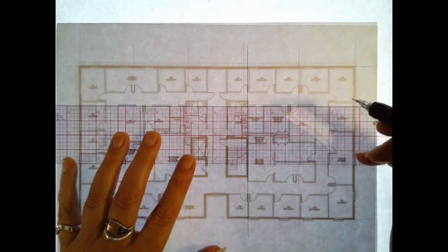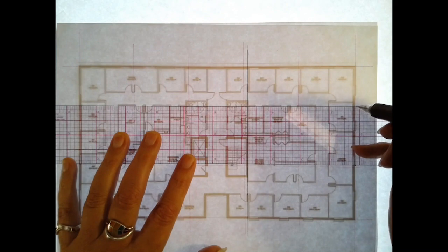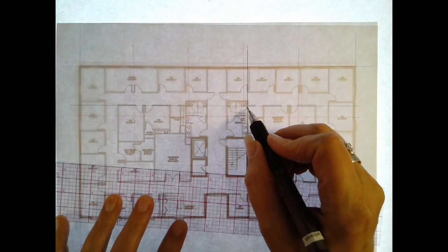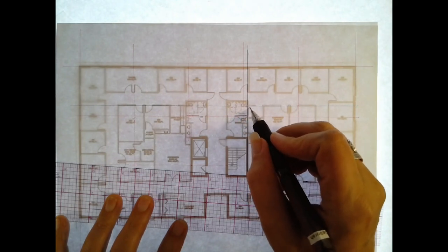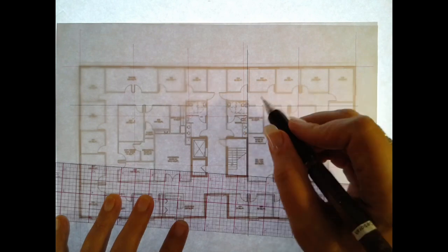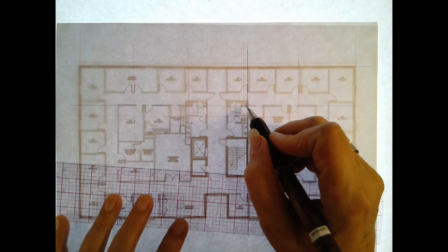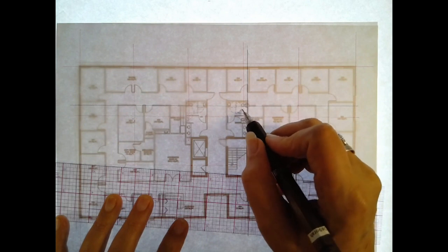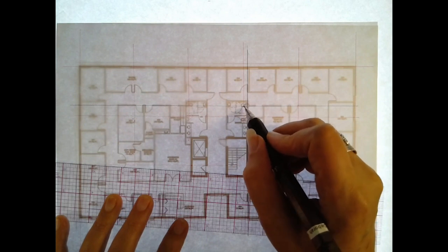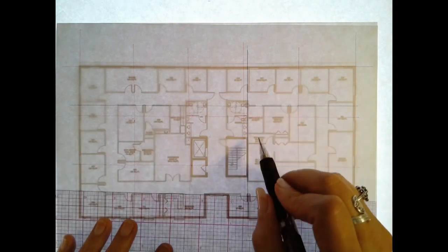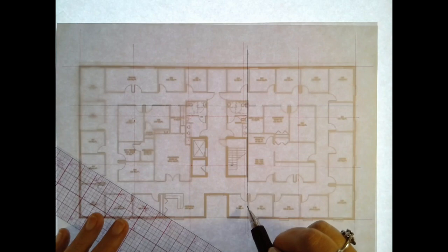We might have to make some changes to the architectural plan to make the structure work. That's sometimes something we have to go back and forth between. So this is okay, but remember the column has dimensions, maybe depending on the size of the building, but we'll say it's an 8x8 column, maybe a 2 or 3 story building. There has to be some shifting with this because the plumbing wall is going to run into the column. But that may be the best we can do here, unless we take it a little bit further.